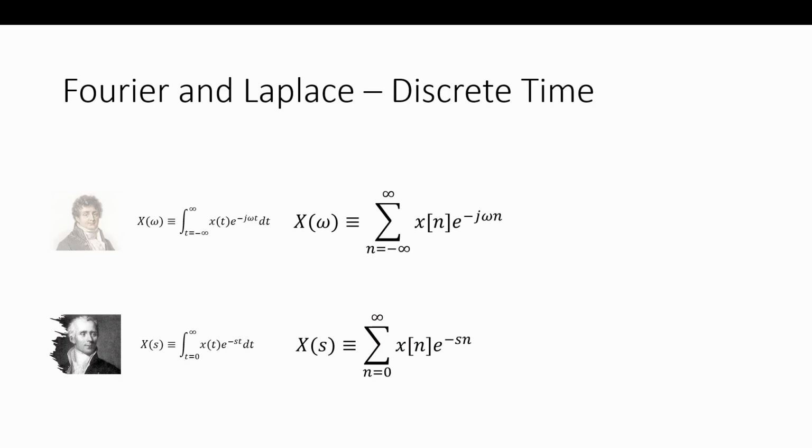So this is a discrete time Laplace transform. We just replace the integration with summations, and t becomes nT, typical. We want to keep time in seconds, so little t would become nT. And then if we say, hey, let's just talk in samples, it's going to be a lot easier. And capital T, one sample. And you see this form right here, x of n e to the minus sn.